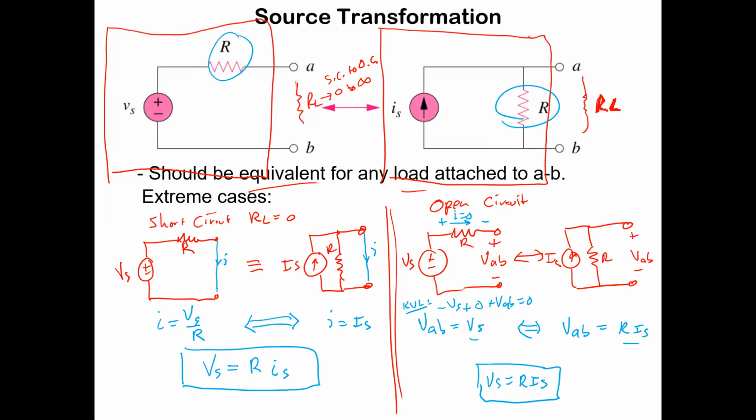Matthew: So does that mean anything with the voltage source, like if it's simple like this? Yeah, it's exactly what I'm saying. You could do this in the lab. You could take your 12-volt source and hook up a resistor in series with it, but have an open circuit. Gosh, we should do that, right? I never do that in the lab. You're going to have opportunities to do that, but it's just really hard to get over. Once you realize there's no current flowing through R, there's not going to be any voltage drop from that, so it's going to read the same as your source voltage.